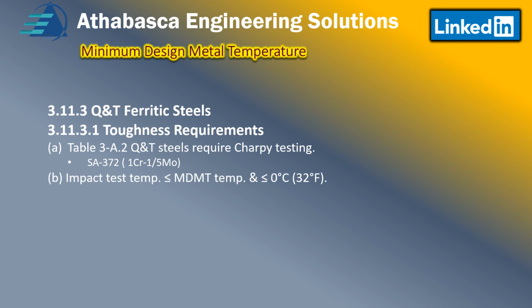Another thing is the impact testing. If impact testing is required, it applies if the temperature is equal to or less than the MDMT, and it is less than 0 degrees centigrade.